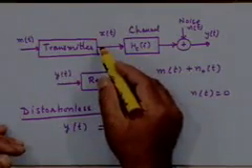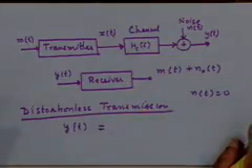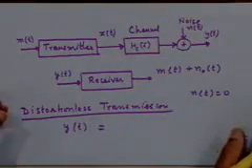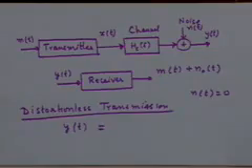The other thing that I can tolerate is some delay, that propagation delay. After all, the signal has to physically propagate from one point to another point, and no matter what form it propagates in, it will take a finite amount of time to do so, and therefore there will be some delay. So as long as the received signal differs from the transmitted signal only in terms of a scaling factor and a constant delay, that's acceptable to me as a replica of the transmitted signal. Do you agree with that?